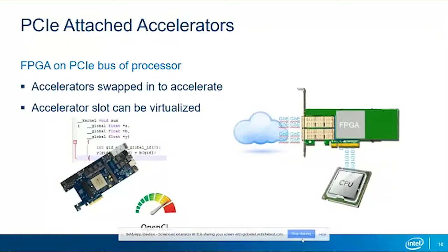This software-based flow enables software engineers to target FPGAs without really having detailed knowledge of the FPGA itself. Now, from the perspective of verification, they'll be targeting a particular board with a particular board support package. The rest of this presentation in terms of the verification of partial reconfiguration applies to the engineers that create that board support package such that the software engineers can target the FPGA.